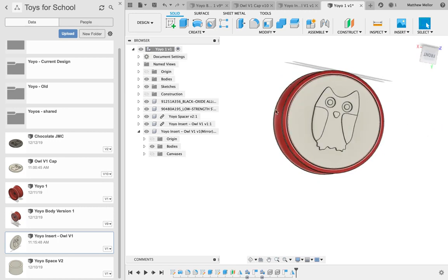We could certainly add some more decoration around the sides, but you guys have now been introduced on how to trace a drawing. So after you've created a JPEG, you've taken a picture of an image, you can insert it into Fusion 360 using the insert tool right here. And then that's it. So for this assignment, all you have to do is take a screenshot once you get to this point and submit it.